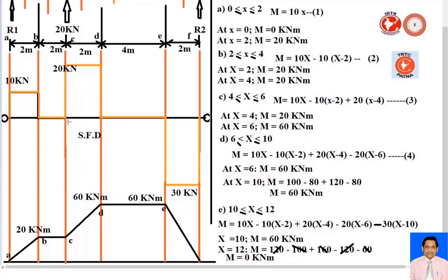How do you verify whether the shear force diagram and bending moment diagram are right or wrong? First, where the shear force value is constant at 0, the bending moment is constant. Just watch. Second step: the difference between 2 points of the bending moment diagram is equal to the area of the shear force diagram. Again I will explain.